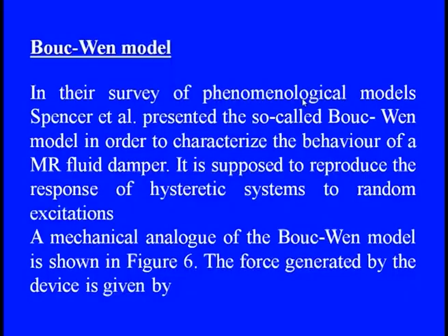which can simply show the real character of the magneto-rheological fluid, which can also act as a damper. Second, a more refined one is the Bouc-Wen model. The Bouc-Wen model is one of the most refined models, which was even presented by Spencer in their paper.